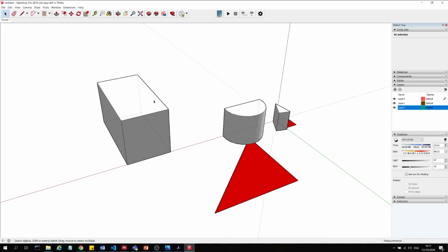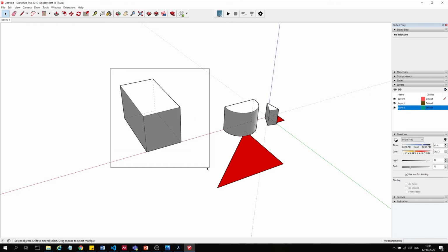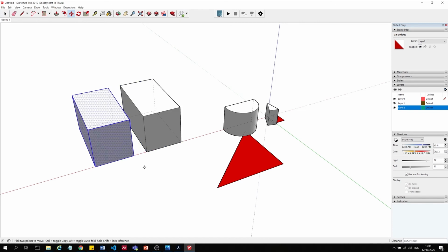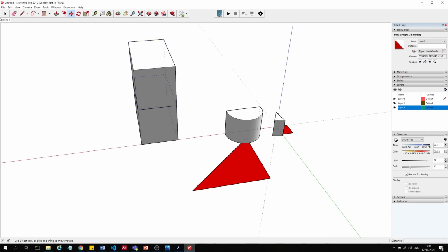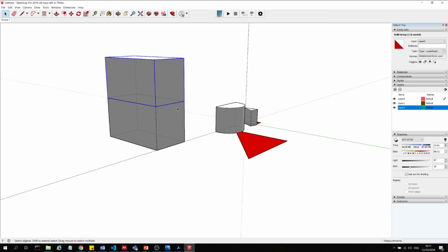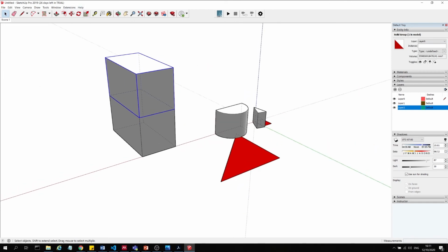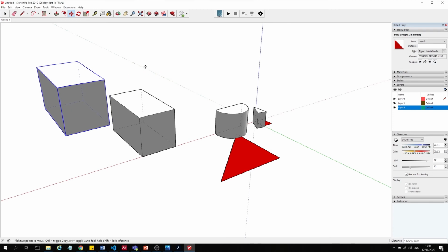The only case where this applies is where you have groups. So in this case, all I want to do is copy. The way I copy is just hold down Control, and I can copy an object like this, click on Escape, and now if I go here and group my geometry like this, so right click, make into a group. Now if I move that geometry to the top over here, you would expect this to influence the bottom half of the box, but because it's in a group, SketchUp will understand that they are isolated and they should have no relation to each other.